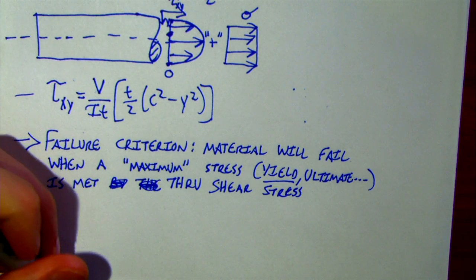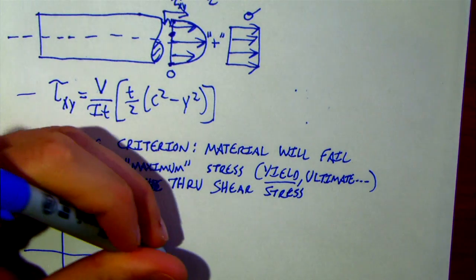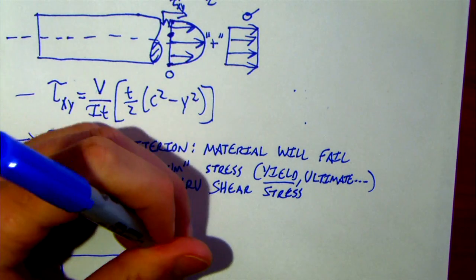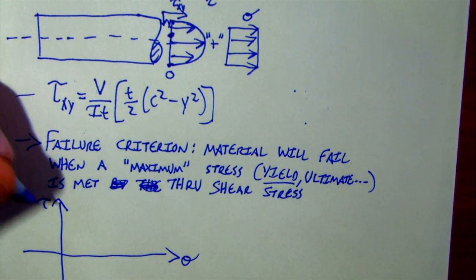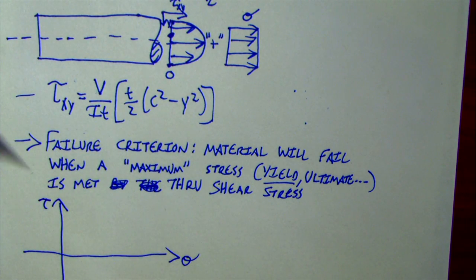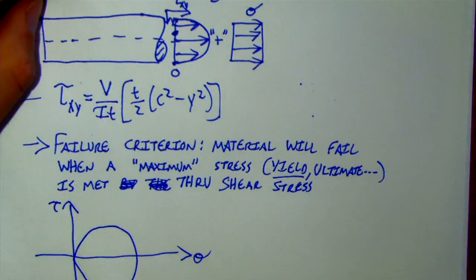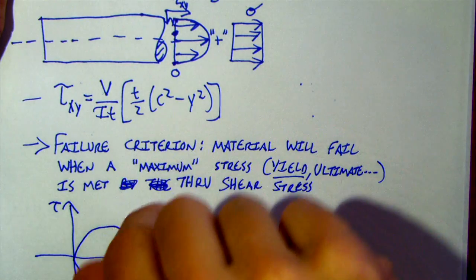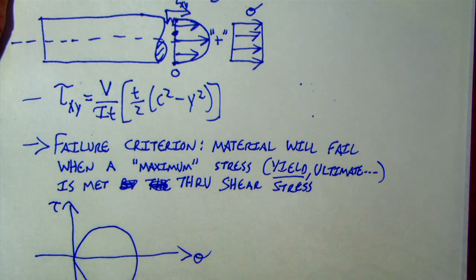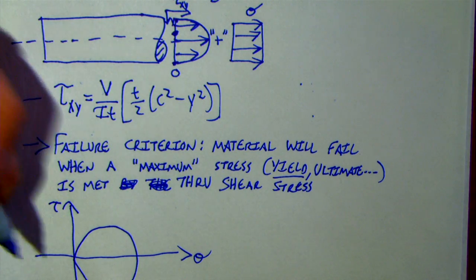And we've said through Mohr's circle that even if something's in pure tension, we can draw this circle, which is really just stress transformations. It's turning that stress cube around, right? It just changes the angle that the thing's going to fail at.